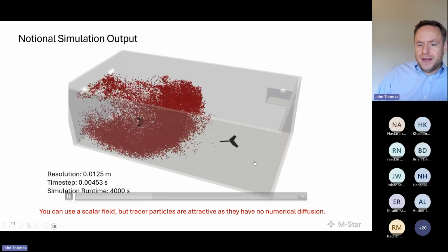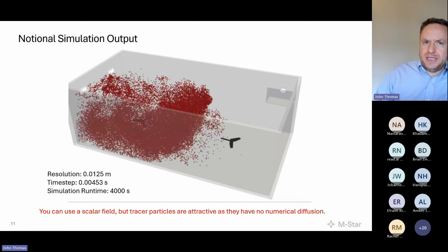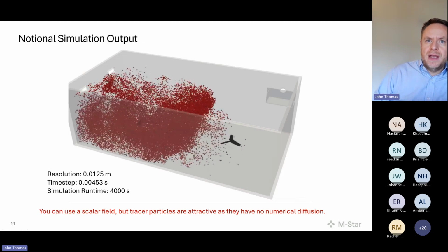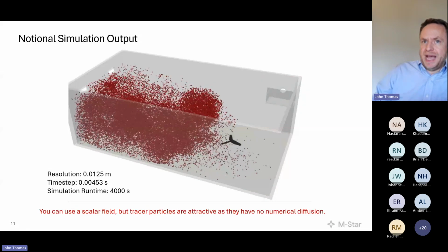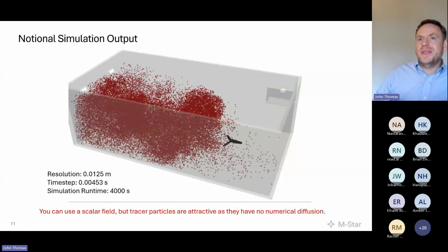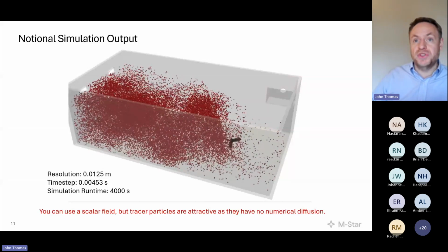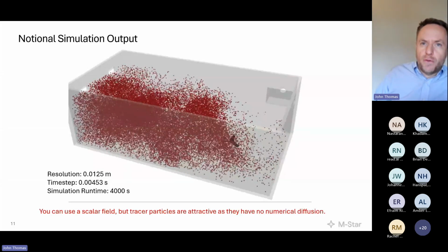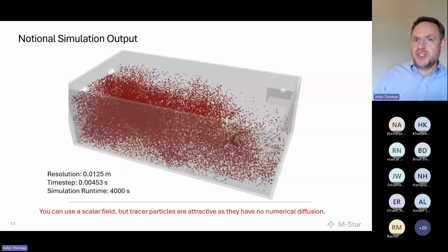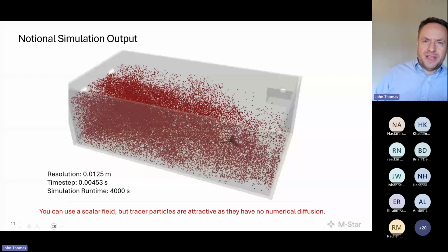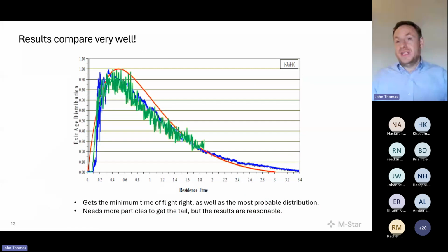And so foundationally, yes, this is a wastewater facility, but because we're solving physics at the level of the transport carriers, and because we're appealing to conservation law, specifically conservation of mass, momentum, and energy, it doesn't matter. It could be a room. It could be air. These particles don't care what fluid they're in. What they're solving is a general transport equation that is extensible to things beyond just closed, agitated vessels. And I think this illustrates that nicely. And more importantly, it serves as a test bed for validation.